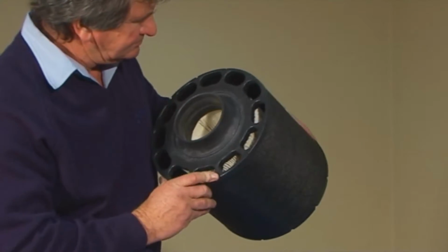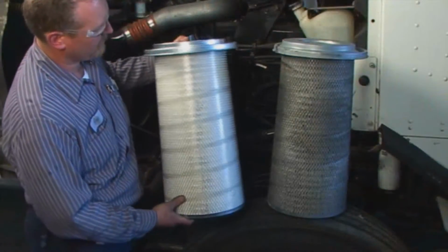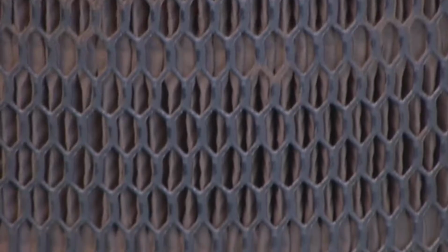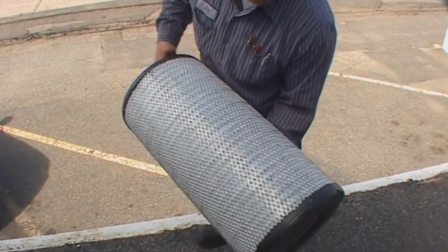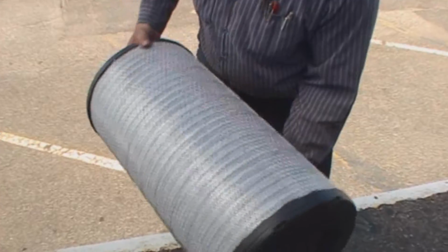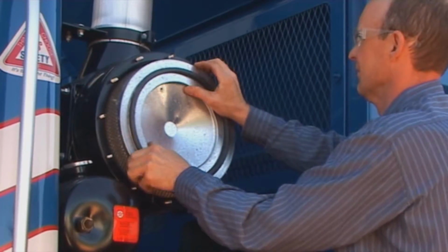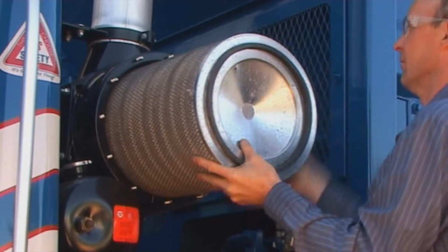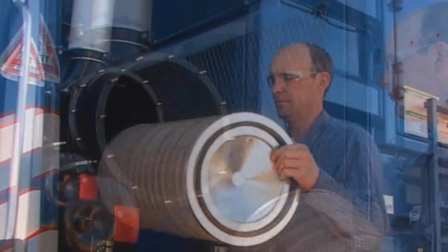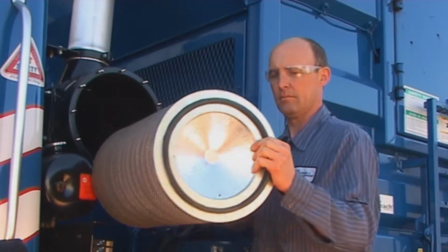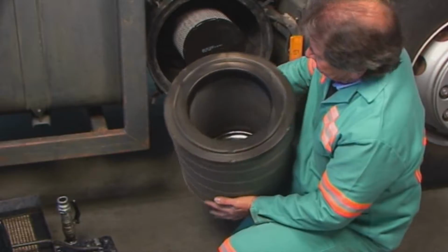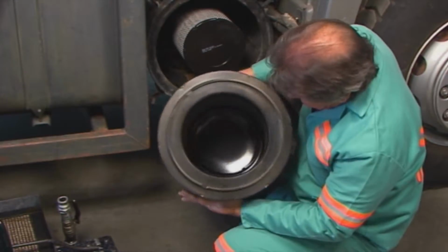Opening up your air cleaner housing to remove the filter for a visual inspection is not recommended. Visually inspecting an air filter can be misleading and inefficient too. A dirty-looking filter may still have a lot of service life left, and a clean-looking filter can also be deceiving. You can't see the dirt that's embedded deep within the filter media, and carbon contamination may not be visible to the eye. Over-servicing and excessive handling of the filter may damage it. The clean side of the filter and the air intake pathway may become contaminated.